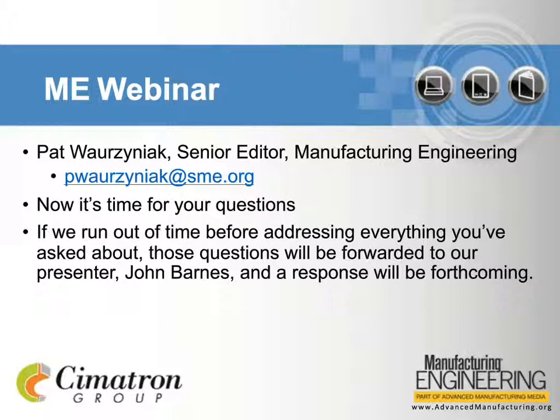So we had one that was really quick at calculating but wasn't super accurate, and we had one that was super accurate but wasn't quite so quick at calculating. And now in version 12, we have just one stock model that's good at both, and the quality is really amazing. I'm really excited about how great this new stock model is. It's true 5-axis, so any way that you flip the block around and over, it knows what was cut, even 180 degrees apart. So I guess for me, that's the most important thing.